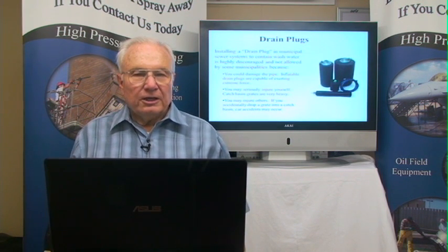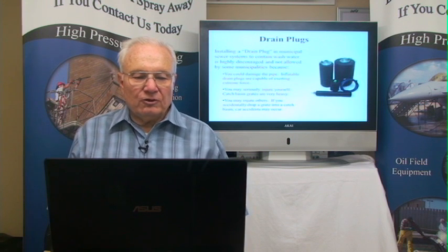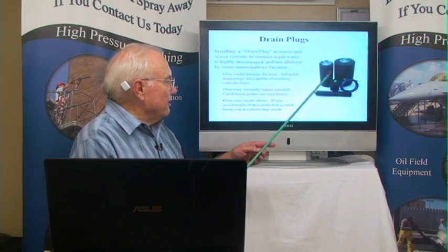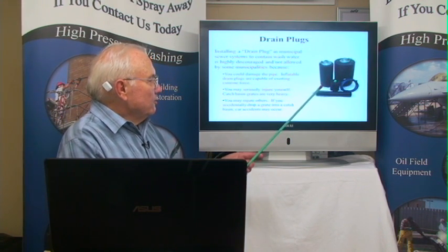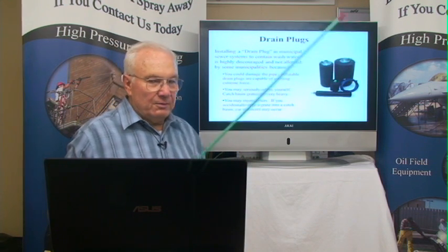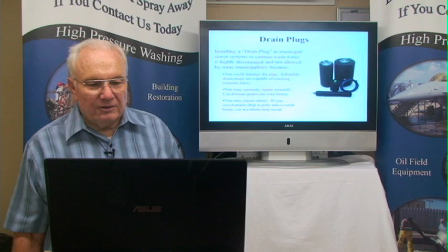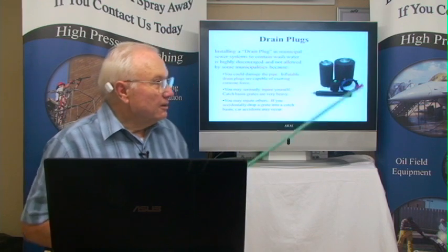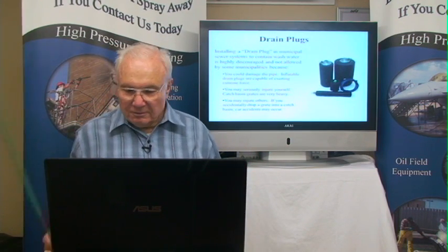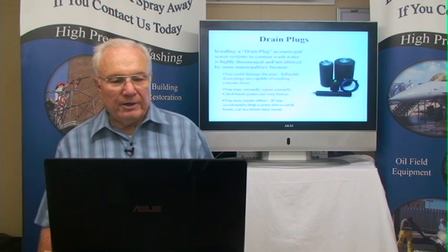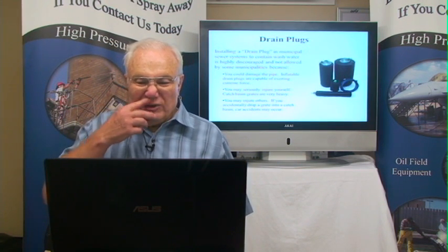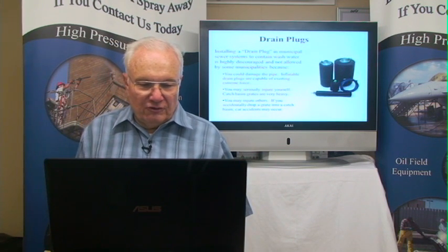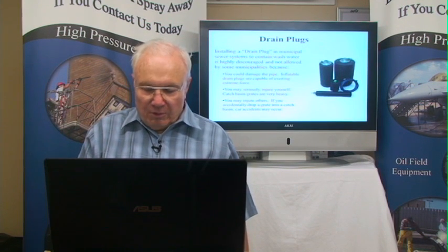Installing drain plugs in the municipal sewer system to contain wastewater is highly discouraged. The reason why is for these to work, you put air in them. We've had several situations where the contractor's personnel put too much air in them and blew up the storm drain system. So if you use these, there's a risk. And the risk is you might be repairing a municipal storm sewer system because you put too much air down there. I want you to bring those to their attention so at least you were aware of that particular product.